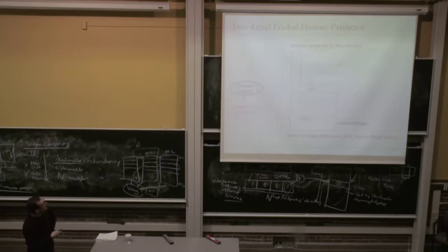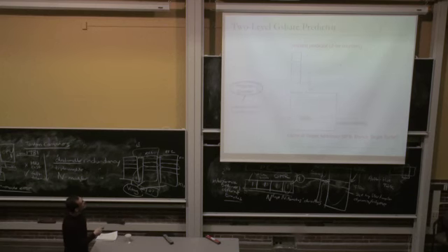2-level history predictor, again, this part remains the same. Now you have global branch history to index into the direction predictor, but you still need to index into the BTB with the program counter to get the target address. 2-level G-share predictor, basically you XOR the program counter with the global branch history to index into the direction predictor. Make sense?